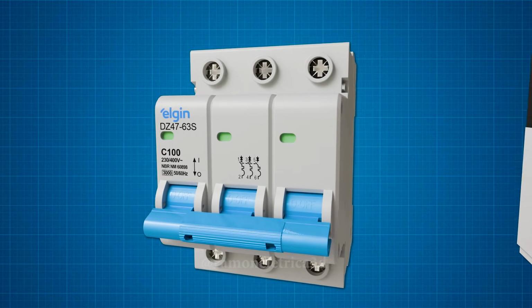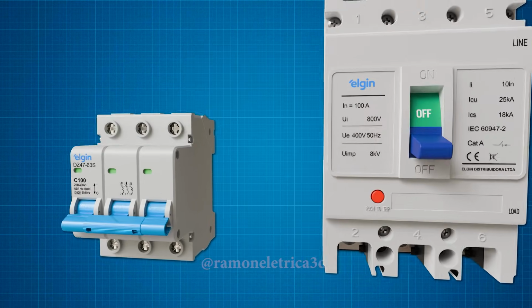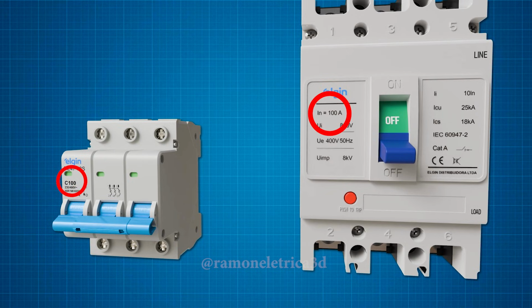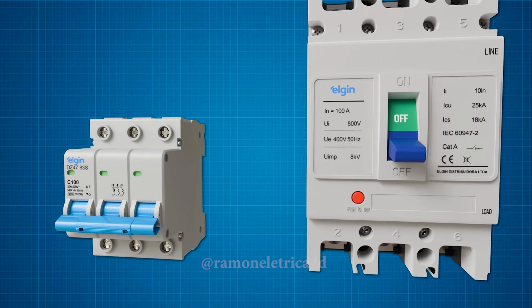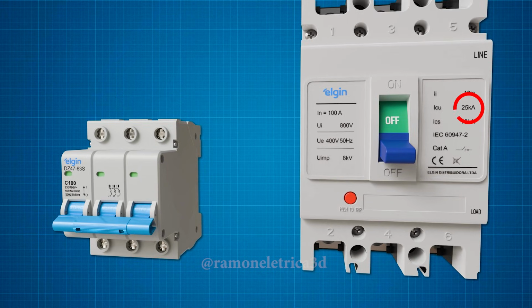Here is an example of two breakers, both rated at 100 amperes. One MCB with a 3,000 ampere short circuit rating and one MCCB with a 25,000 ampere short circuit rating.